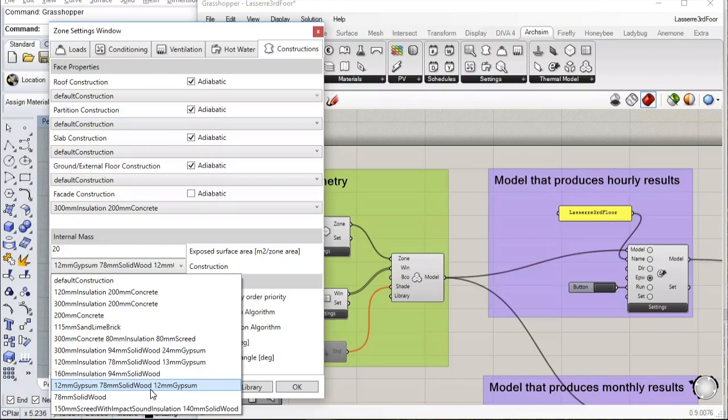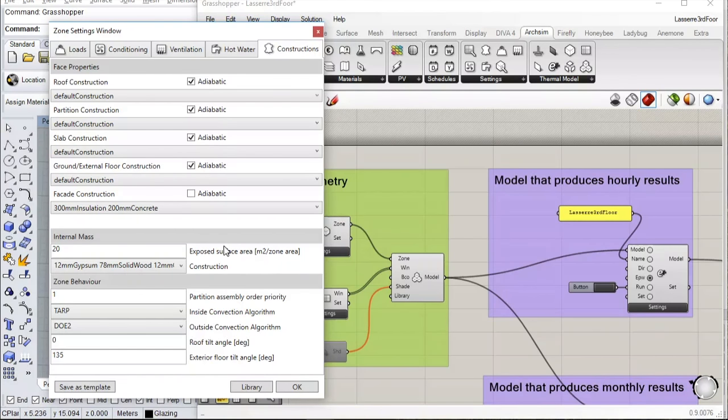This value, what you specify here, can do a lot to affect not only the accuracy, but the variety of results you get from the simulation model. So you may want to be conservative here with internal mass and pick as small a value as you think is appropriate. Not too small to be impossible or unrealistic, but perhaps your most conservative guess for the value of internal mass.